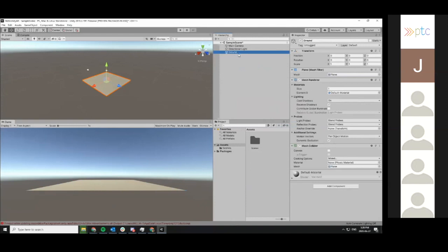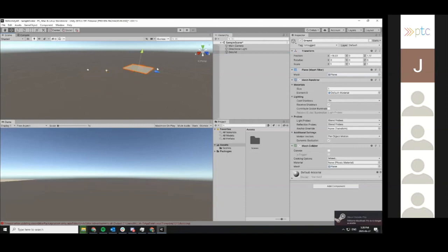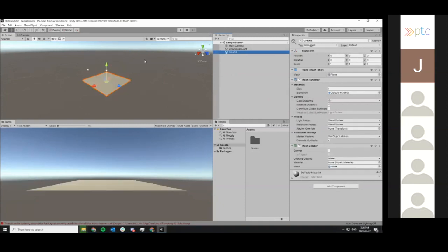When you create game objects in a scene, sometimes they don't actually appear in the center. They'll appear off into the distance or something. So this is why we need to reset the transform of the game object sometimes. To reset it, you go over here in the inspector, and then you click reset. All right, so now it's at the origin.